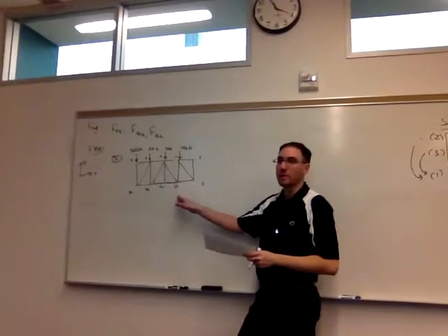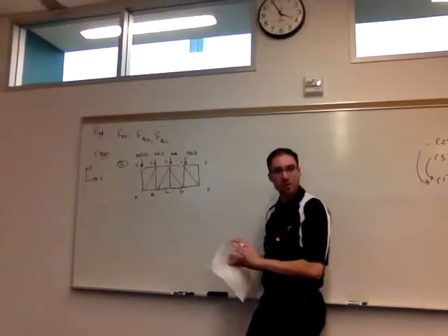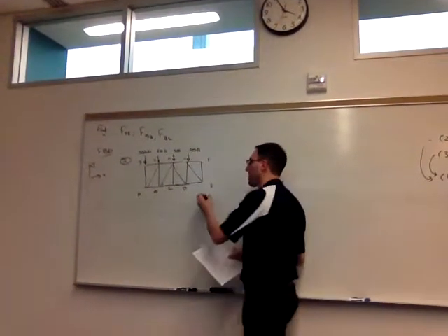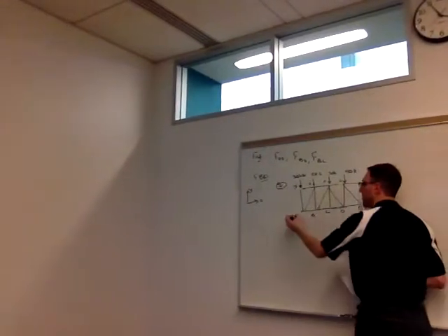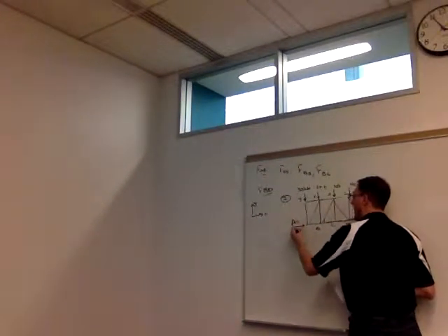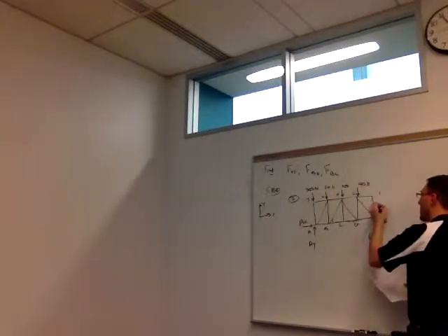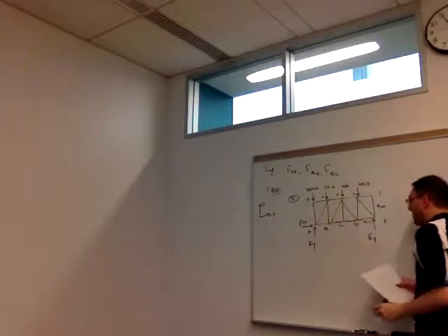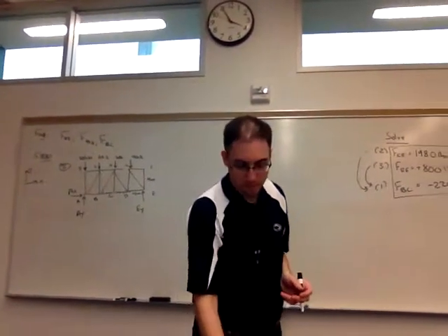So the support reactions we have here, this is just like a chapter 5 question at this stage. Nothing is internal in this picture. The roller is going to have an EY, just that normal force. I'll have an AX and I'll have an AY. And in this problem, all of the spans are 4 meters long.